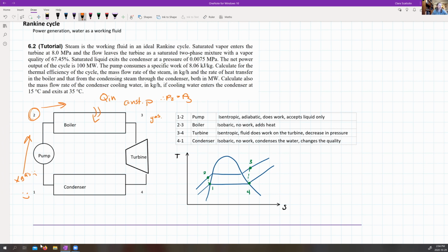So we're boiling it basically until we hit gas. We need to hit the gas state, and then we send it through the turbine. What the turbine does is extract work. We get a work out, which from our sign convention we know should be positive. This is the useful portion of the cycle. The turbine is what we want. We want to maximize the amount of work coming out of the system, because as I said, it's a power generation cycle. We're boiling water in order to hopefully get electricity out of it.